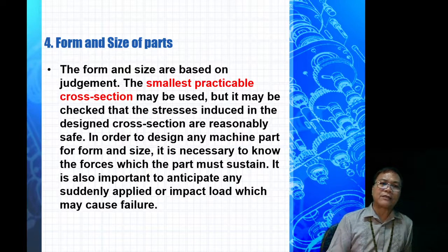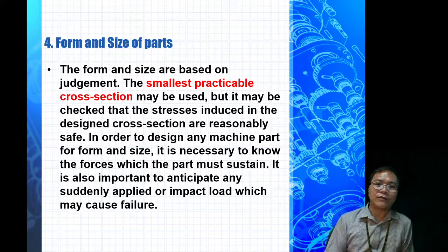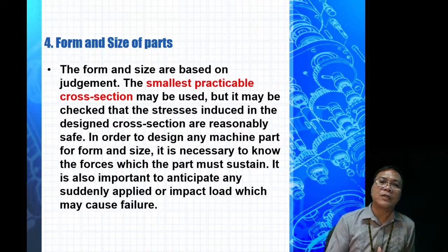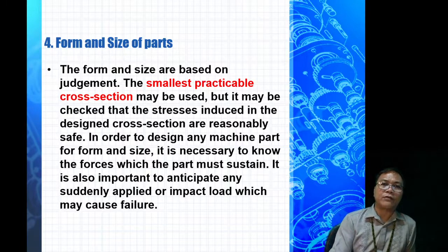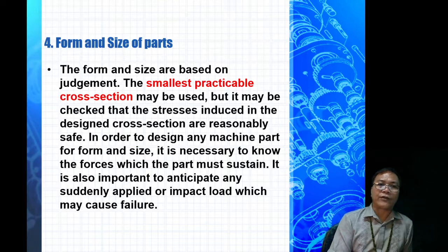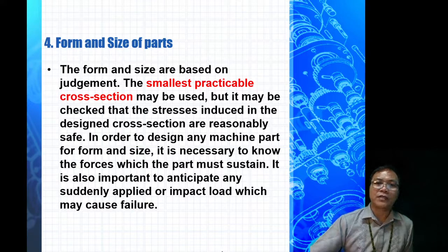It is safe, no, to have the bigger size of cross-section of the shafting, but it also affects the cost, no, not only on the cost of that specific part, but it also affects all other parts, no. Okay, for example ang bearing, it has to be bigger also, and all the parts kay bugat na siya, it has to adjust also the sizes of the frames and all other parts, no. So you have to really make a computation and in the design decide how big or how small is that specific part.